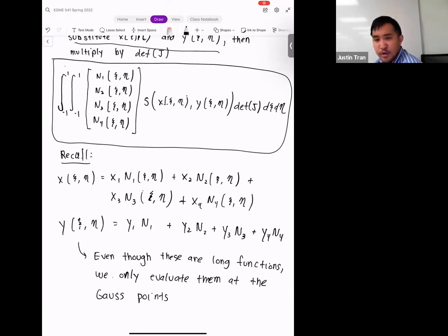And so it's only about half the work that you do for the element stiffness matrix, again because there are no derivatives involved here. It's just a straight up change of variables for the integration. The only thing is that you might have to work a little bit harder for x and y, as opposed to the element stiffness matrix, which traditionally does not have too much x and y to it, unless you have a spatially varying thermal conductivity. Any questions on this?